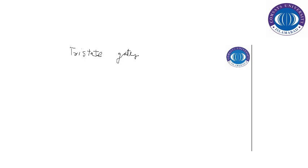So what we have to do is we have to implement basically the 8x1 multiplexer by tri-state gates, and since we have already implemented the function by using multiplexers, we just have to make the interconnections here. So first of all, we are going to use the 8 tri-state gates here.